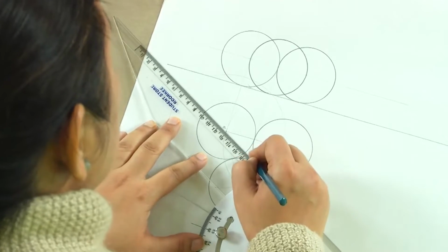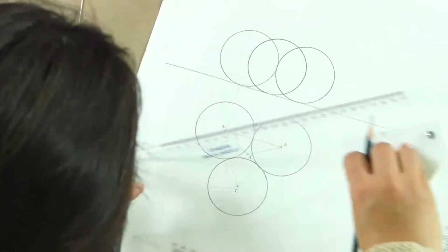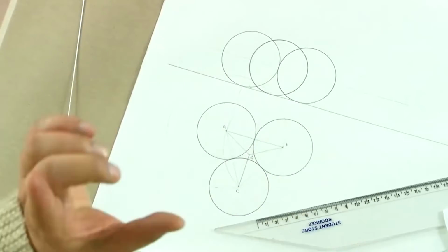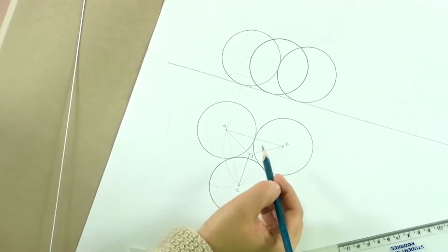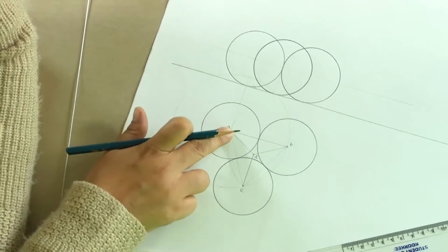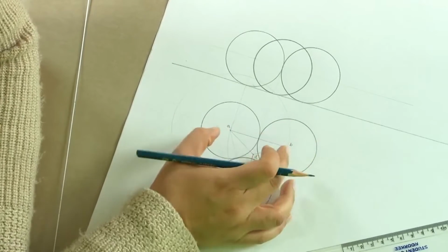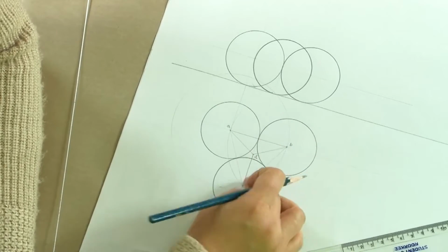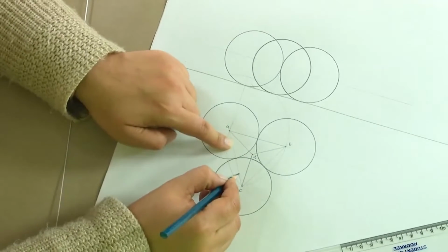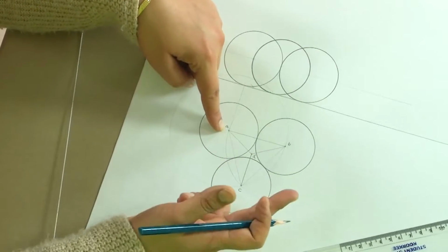So, what we see is this DA, DB and this DC. What is the true length of any of these three lines DA, DB and DC? It is actually twice the radius of this sphere, because the distance between A and B is twice the radius, between B and C it is twice the radius, between A and C it is twice the radius, or it is actually the sum of radius 1 and radius 2. In this case, since it is equal sized spheres, we will have it twice the radius.